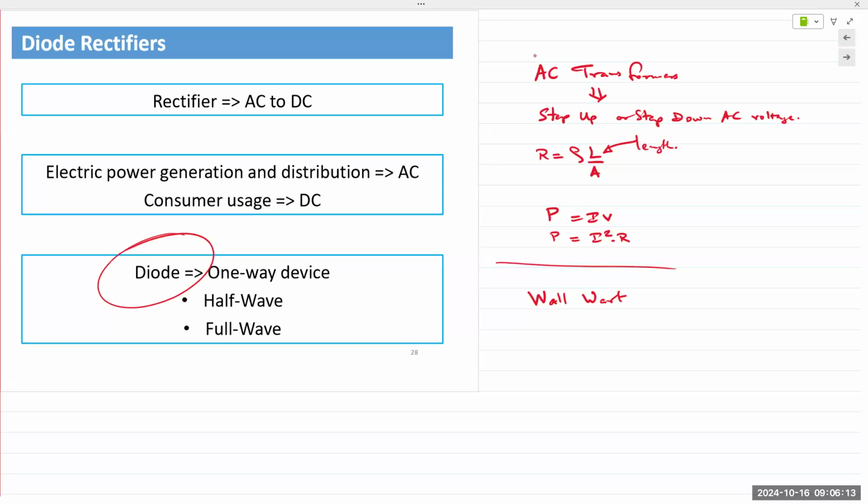But now it's of course changed with the advancement in technology, but they used to be small transformers, and even when I say small, it's like the size of my fist. So small transformers that would take the electrical voltage from 110, 120 volts and bring it down to like 10 volts or 15 volts, depending on the requirements. And then you take this 10, 15 volts AC and you apply it to a diode circuit. The diode would rectify it to DC and then filter it out, and you get 10 volts DC at the output. They came to be known derogatorily as wall warts, because everywhere you would go, you would see those plugged into the walls for every single appliance.